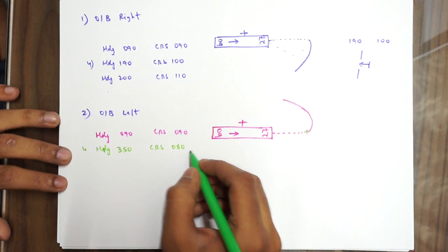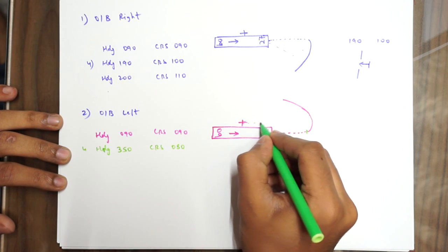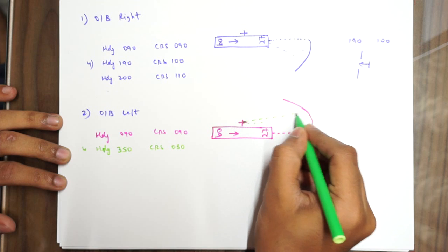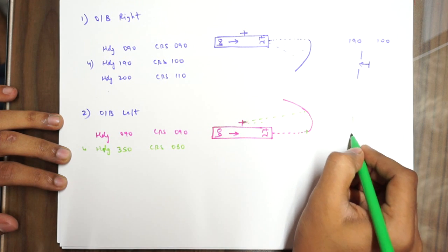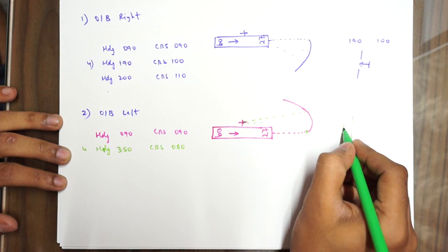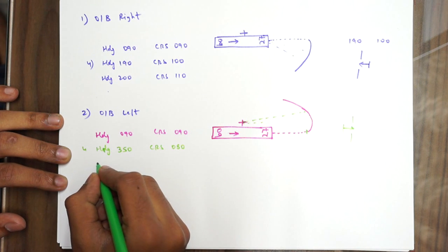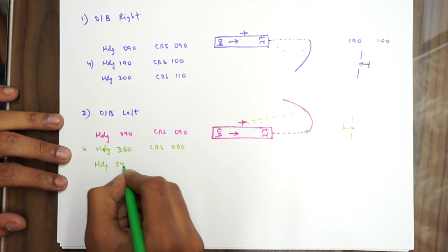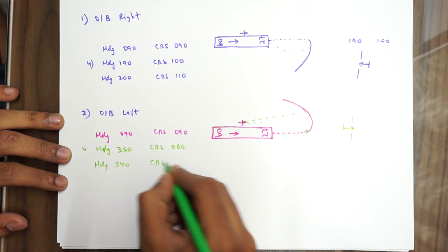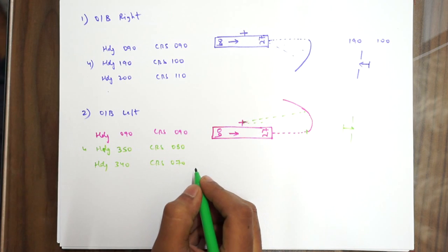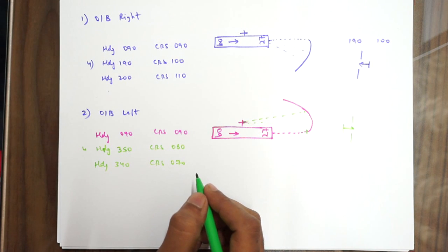Okay, so with this what will happen is, 080 is somewhere here, and you will be established, and this will be the position of your needle. It will start moving to the center, then start changing your heading bug to 340, and just keep decreasing 10 degrees. People do it for 5 degrees as well to improve accuracy.